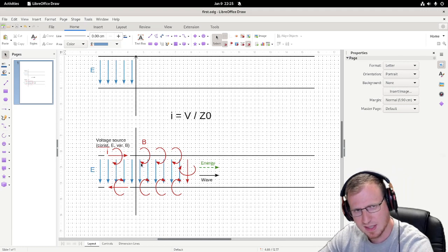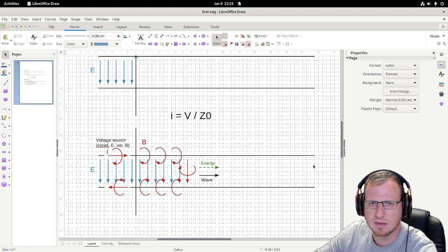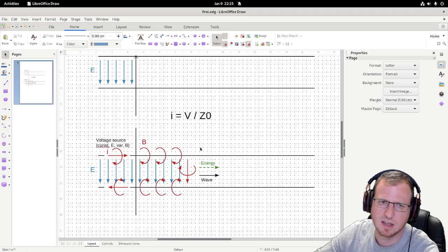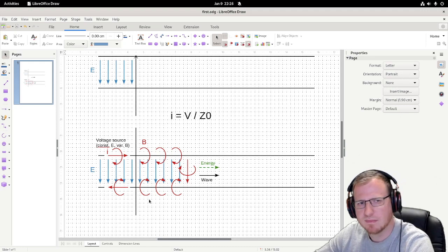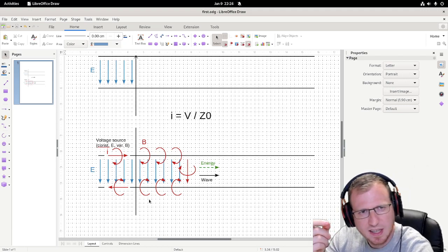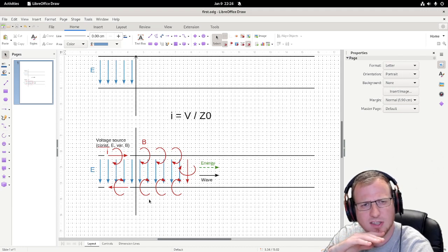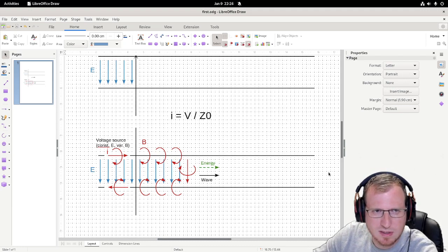And that's very interesting because that means it's not depending on the load. The current at the first instance is not depending on the load, but on the geometry and properties of the line. That means at the very beginning, some random current is flowing. And this current has nothing to do at all with the load on the other side, because